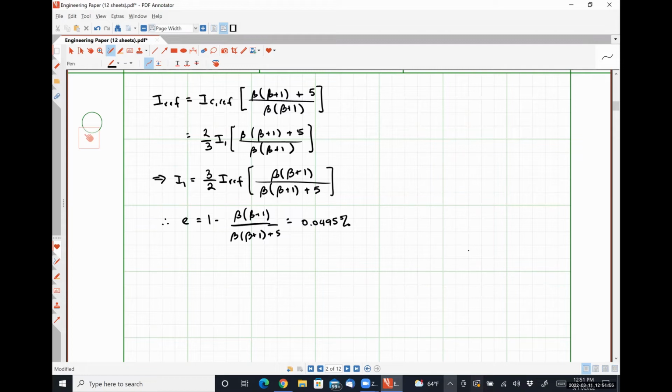For sure, absolutely. We're going to talk about that in just a couple of minutes. But there might be reasons why you wouldn't want to use MOSFETs, like if you were trying to make a device. So I think we talked about this briefly at the end of 335 as to why you would ever use BJTs when MOSFETs exist. BJTs handle larger amounts of current better, right? MOSFETs are great for like microamps of currents and things like that, but for power amplifiers, BJTs, or heaven forbid, vacuum tubes all the way, if you need it to be real beefy.